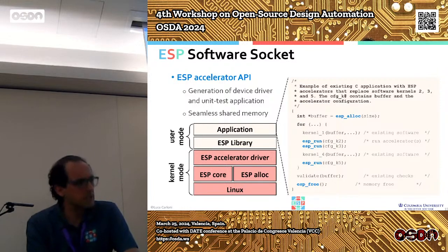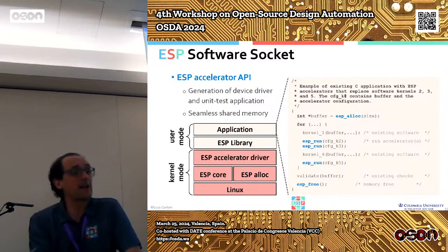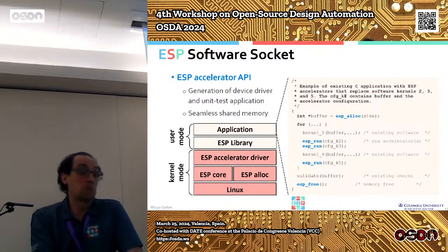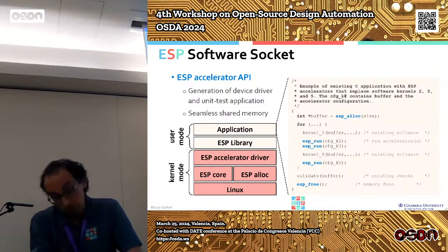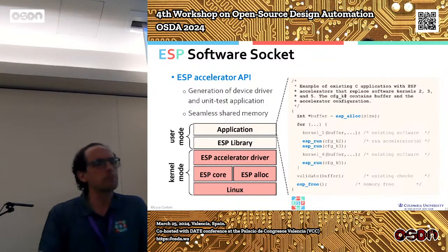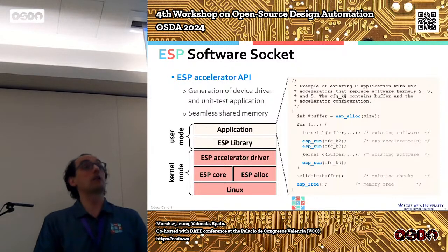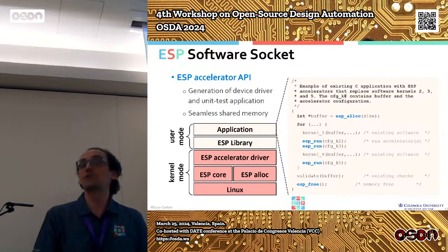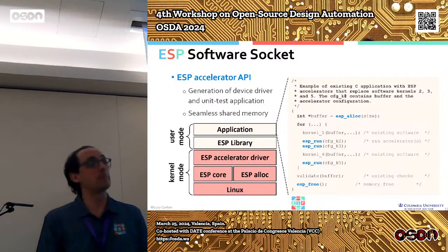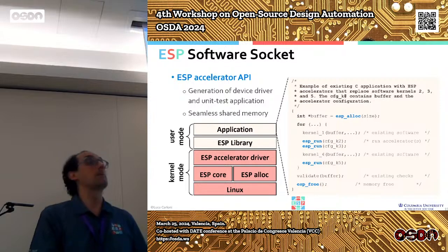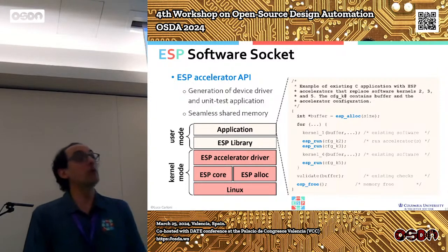So these accelerators, they are loosely coupled, execute tasks which are coarse-grained, typically accessing very large amounts of memory, typically in DMA, although we support also some types of coherent access from DRAM. So when you access a lot of memory, this accelerator executes for millions of clock cycles. Of course, this is still better than executing the same task in software, taking maybe hundreds of millions of clock cycles. So how do you invoke this accelerator?